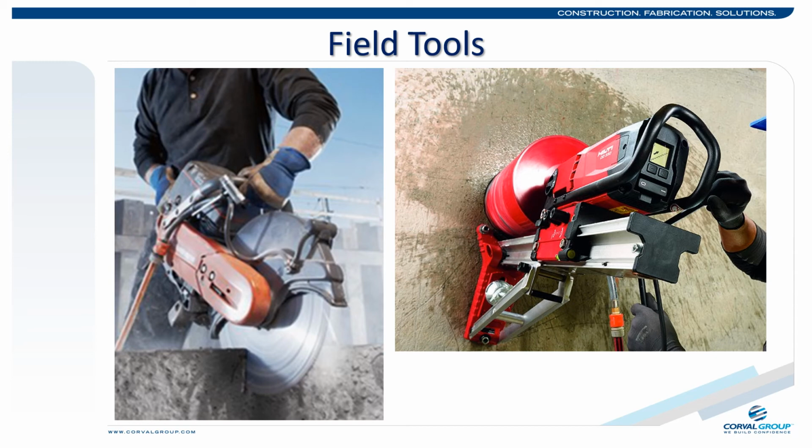The water application can be done by another employee who is dressed in the same level of PPE as the employee operating the tool. On occasion, providing water to a construction site can be a challenge, but it simply cannot be overlooked if it is required for silica exposure. This may bring forward another opportunity to use stop work authority. Many long-standing larger tools have always used water as a means of lubricant and to cool the tool attachment, blades, discs, etc.